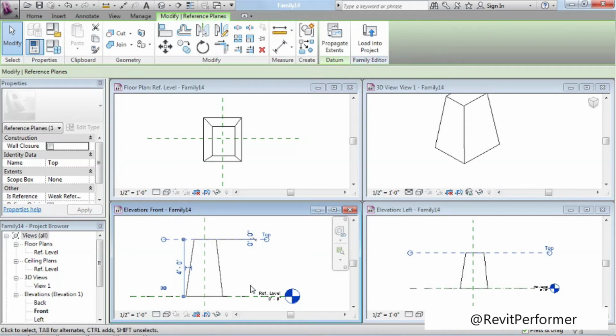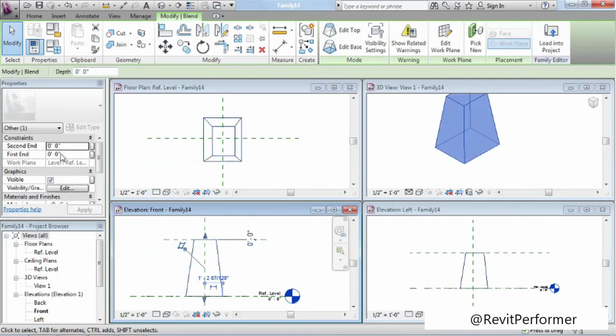But personally, there was an error involved in this approach, and there wasn't an error involved in the previous approach with the parameters. So personally, it's my recommendation that you use the first approach, where you draw both sketches on the same work plane and use either parameters or the properties directly here on the properties palette to control the height, rather than trying to put the two sketches in two different work planes.